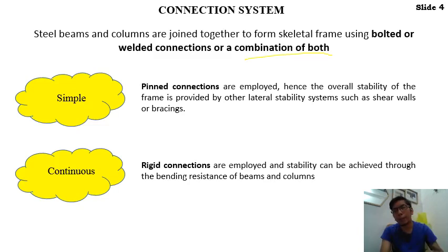However, in a continuous frame construction system, even though you are using rigid connection, sometimes you still need to apply pin connection, especially in a high-rise project, when you reach level 10 or 20 floors. You can't just go straight to welding. Maybe you need to apply pin connection first, using bolt and nut, to get extra stability, and then you apply rigid connection.